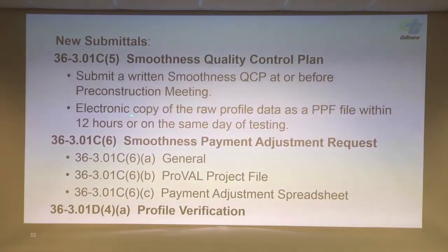And we have requirements for the PPF files. These are the raw data profiles that come out of the inertial profiler. The inertial profilers can give you a lot of different formats. This is the standard format. It's just raw data. All this file is just elevations. There's no IRI data in it. It's just PPF, just elevations. We feed these into ProVal to come out with the IRI values.